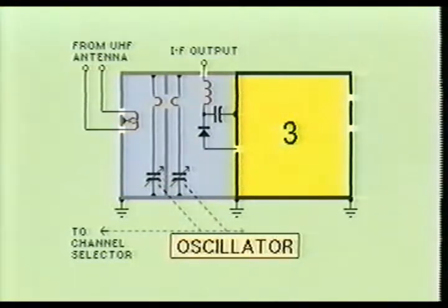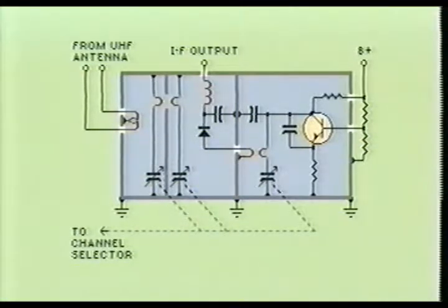The third compartment contains the UHF oscillator circuitry. It is basically a modified form of the Colpitts oscillator configuration called the Ultra Audion. Notice that this circuit uses the silicon epitaxial planar transistor as the primary active component of the oscillator stage. This stage also contains a trimmer capacitor used to adjust the oscillator frequency for channel selection. Also notice the electromagnetic coupling between the oscillator stage and the mixer diode. The capacitors mounted on the metal enclosure are used to reduce unwanted AC frequencies.